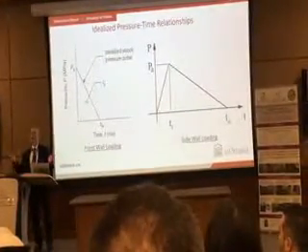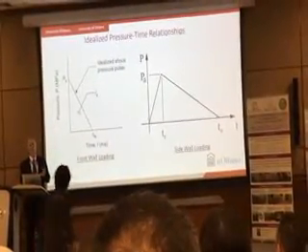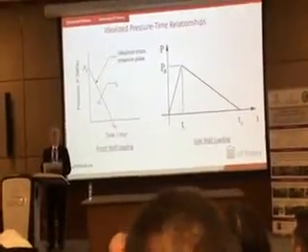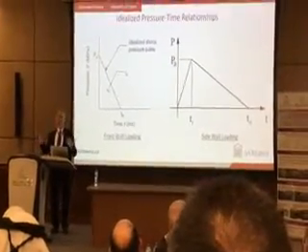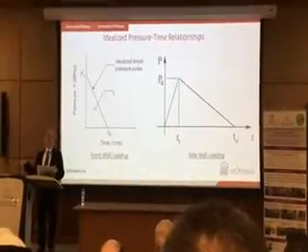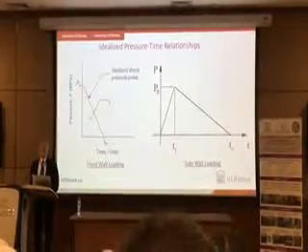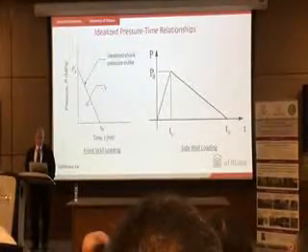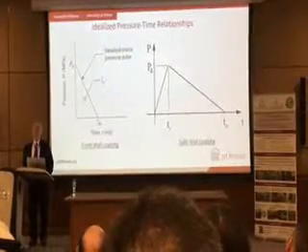Okay, so now we learned that charge weight is one parameter, standoff distance is another parameter, and they result in reflected pressure, and this reflected pressure takes place over a certain time. Now let's idealize these factors so that we have workable scenarios. And after all, we're structural engineers, we want to know building response. And these are the idealizations.